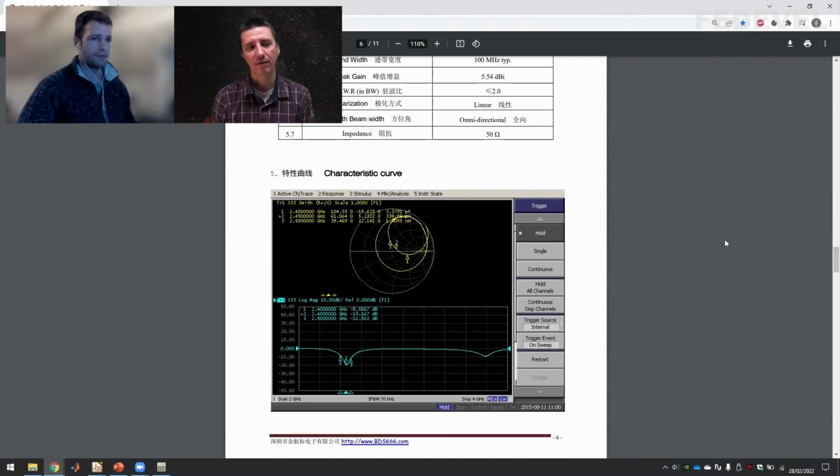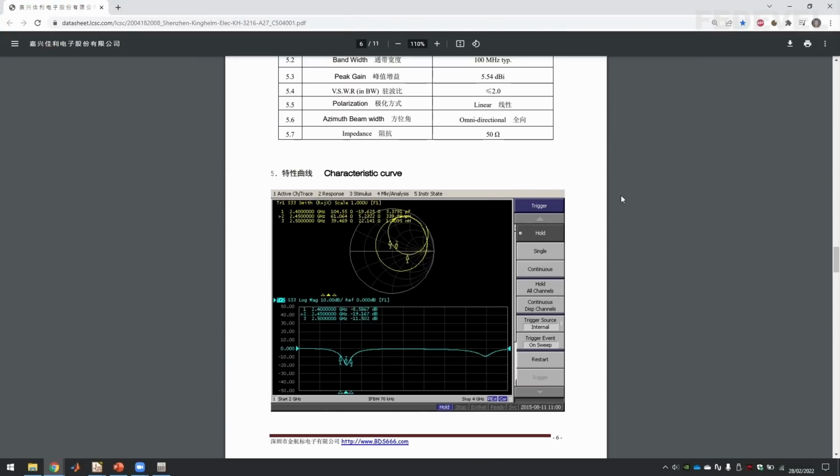I think there are also differences if you would like to make a product from this and go through certifications. Then I think it's always easier to use a module, which should be certified. But if you design your own antenna, I think it may cost you quite a lot of money to go through this certification process. Yeah, that's a very good point. It's a pretty ridiculous thing to do if you have pre-made antennas where you don't have to go through certification or things like that.